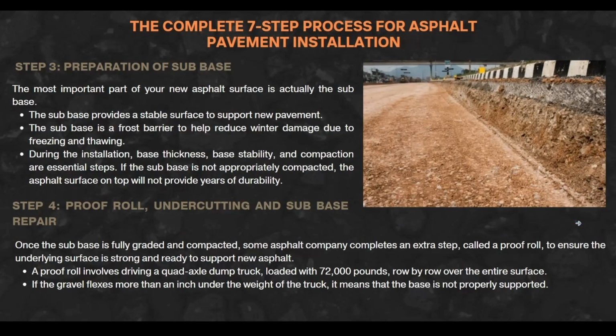Step 3, we have the preparation of the subbase. The most important part of an asphalt surface is actually the subbase, because the subbase provides a stable surface to support new pavement. The subbase is a frost barrier to help reduce water damage due to freezing and thawing.